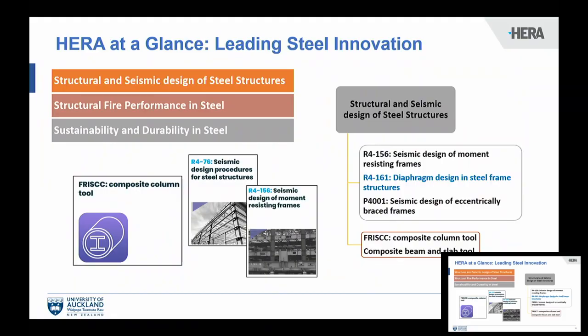In the structural and seismic design, we have many design guides and software. I would like to mention two or three of them here. The most recent one was the diaphragm design in a steel frame, and the other one is the seismic design of moment-resisting frames that will be published soon. And the other one that some of you may know is the seismic design of eccentrically braced frames, P4001.